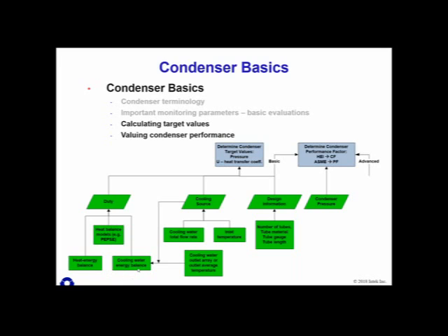It's a cooling water balance. So you can use the inlet temperature of the cooling water, the outlet temperature of the cooling water, and the cooling water flow rate to calculate a duty. Now, a lot of plants don't monitor cooling water flow rate. So the third method, and it's a pretty good method, is a heat input energy balance.